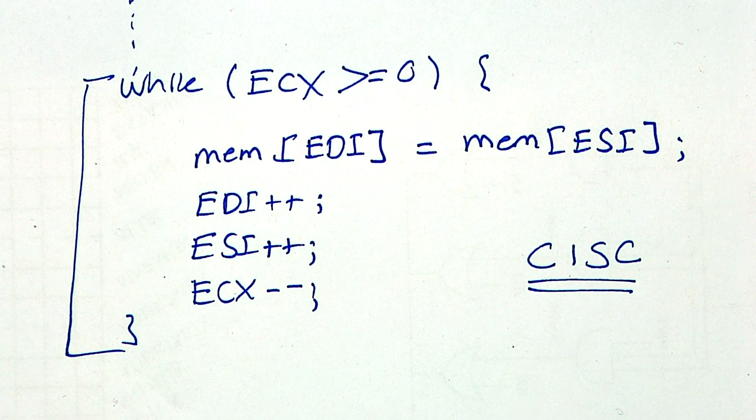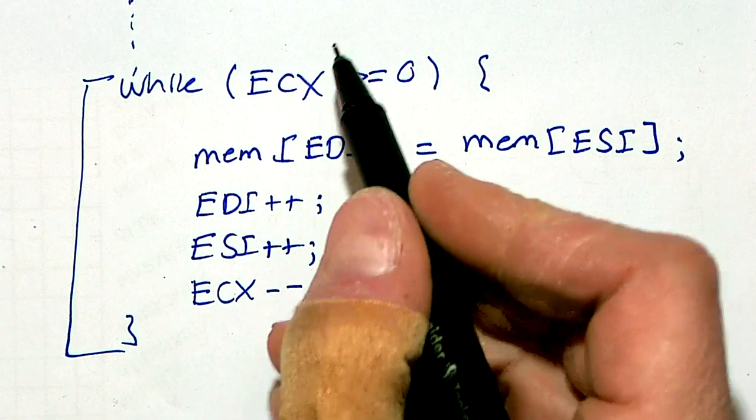That's one way of designing a multi-cycle machine, actually. You treat an instruction as a sequence of micro-instructions and design a control logic such that it sequences through those micro-instructions. Now you can do many, many things. You can have your little program inside an instruction. You could branch. In fact, Intel calls these micro-branches, because they're not real branches. So this would be a micro-branch, for example.